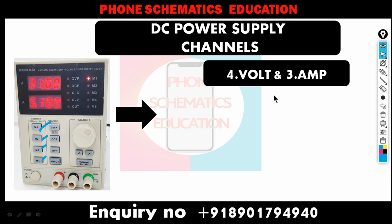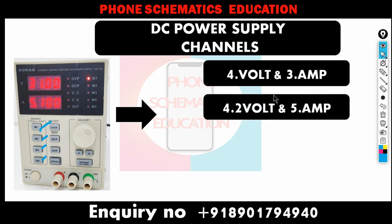Right, now second, 4.2 volt 5 amp. Sometimes I use this also with the multimeter probe. I use multimeter probes. If I find a short circuit in a primary line, then I use this one attached with the multimeter probe. That's on a 5 amp, and we find the short in a few seconds.